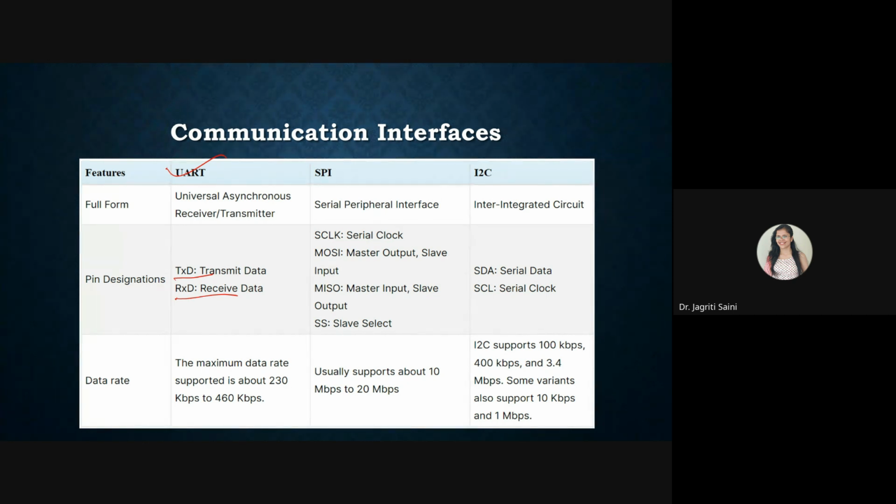So when it is written as A0, D0 or analog and digital like terms, it means you can connect accordingly on the analog or digital channel. But when a sensor has TXD and RXD written, you have to find the TXD and RXD pins on the microcontroller and then you can connect them. I'll show these types of sensors to you in the coming applications.